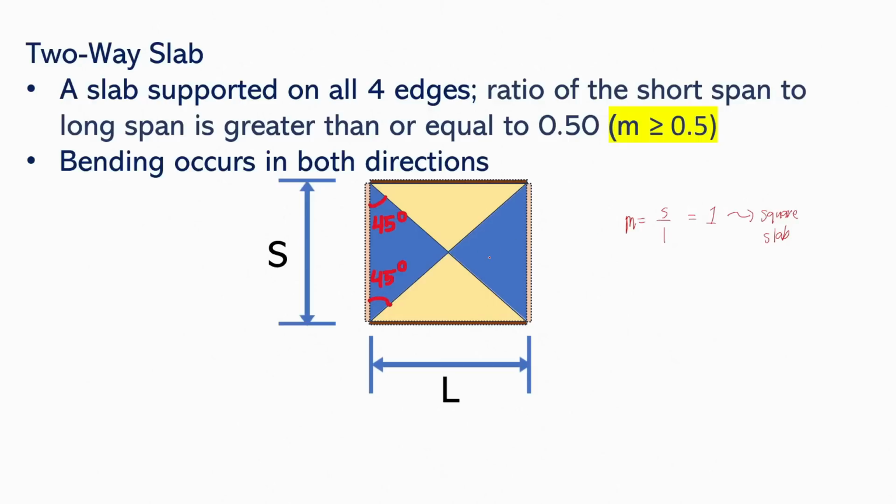If our slab is not a perfect square, then this tributary area will be a trapezoid. Kasi ito kasi yung mangyayari. For example, we have this one. This triangle will be formed along the short span. So, if this is the short span, we will form a triangle dito and also dito. And then, let's say this is the long span. Itong dalawa. We will connect the vertices of these triangles and so, magiging ganito. And so, yung tributary area ng short span will be this area. And then, ito rin. And then, for the long span, we will actually consider this tributary area. Itong trapezoid. And also this one. Now, dito, since square, yung dalawang sides natin are the short span. And so, that's why triangle lang lahat to.